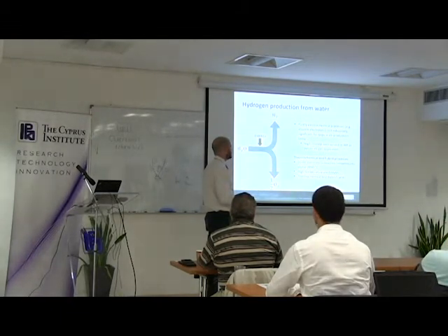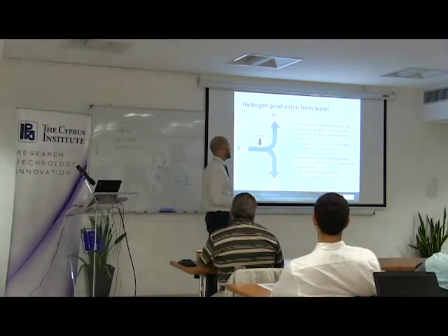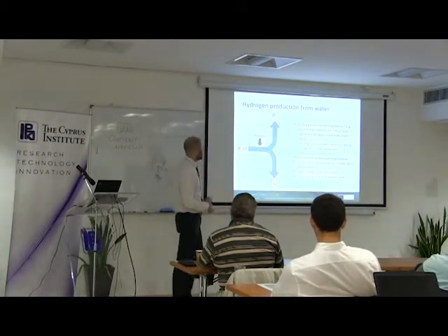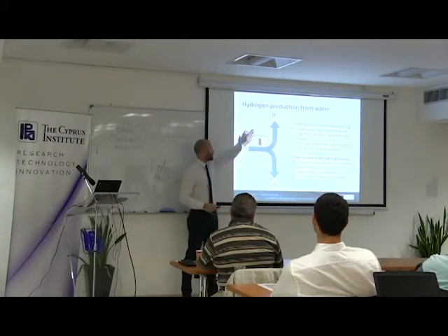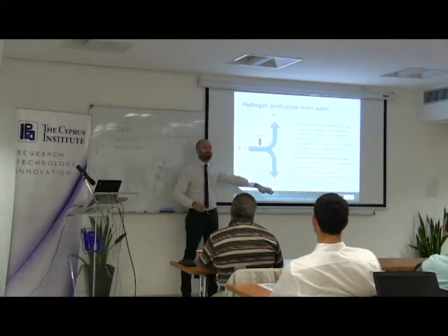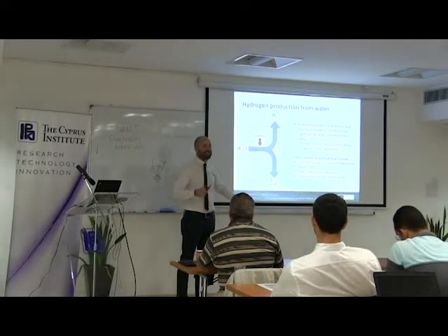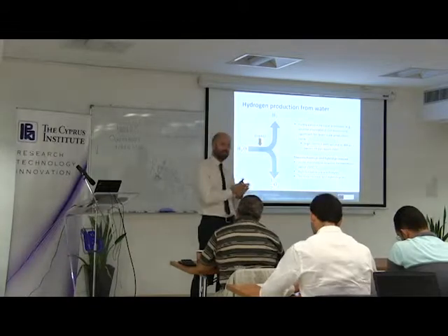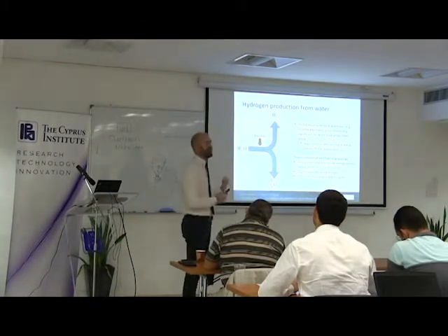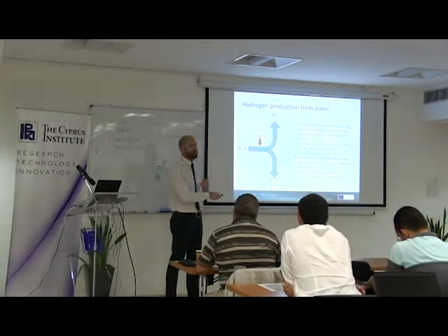Then, if we want to use a less valuable energy input, we can move to thermochemical and hybrid processes. This direct splitting of water into hydrogen and oxygen can also be done with a purely thermal input. But in this case, the second principle tells us I want a very valuable energy type. So either you give it as electricity, or you give it as high temperature heat. But in this case, the temperature is definitely too high.